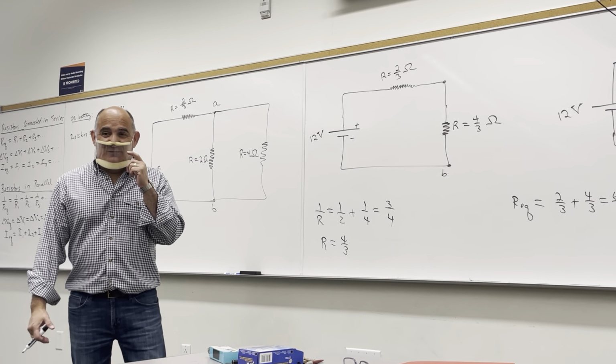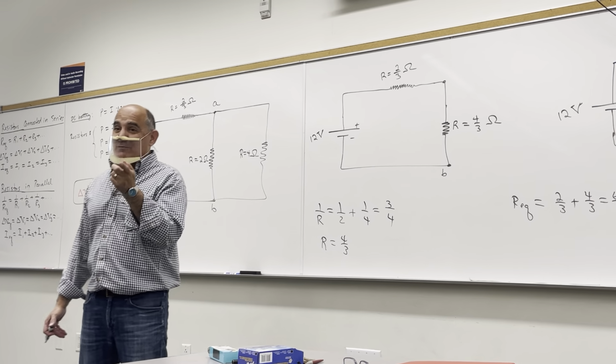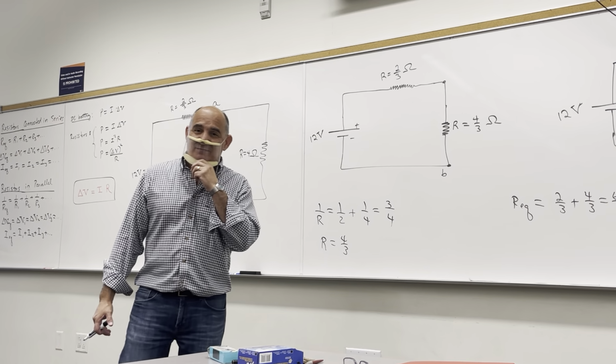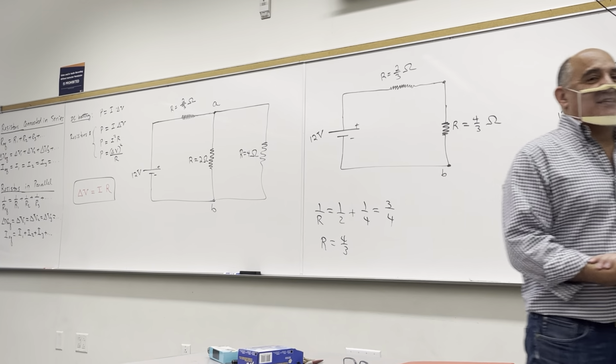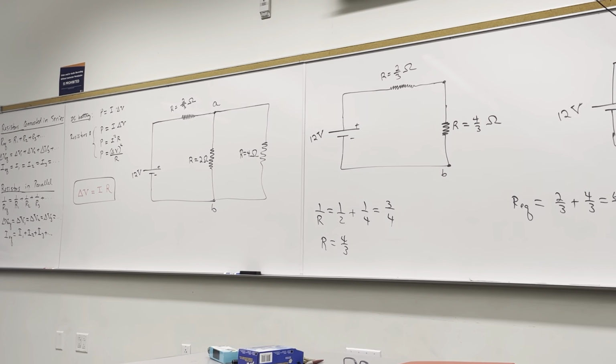I actually figured out which way they move and then flip the direction because by convention, you say that the current is in the direction that the positive charges would move if they could move. So the positive charges will move in the clockwise sense in this circuit. So we say that the current is clockwise, which in the battery, through the battery the current will be up, but in the resistor the current will be down. So that will be 2 amps, okay?